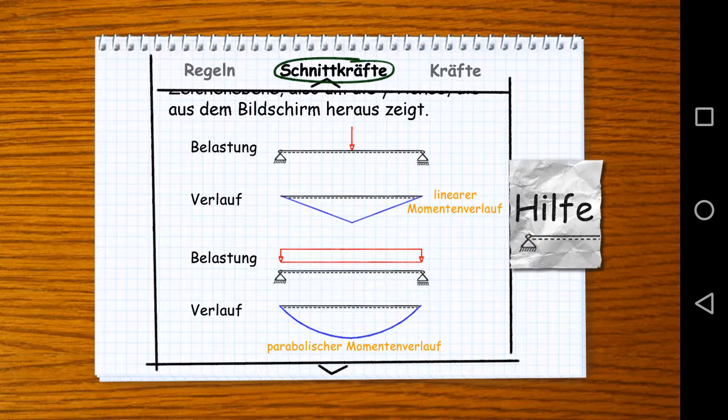Let's look at the example we have here. A single load in the middle of the beam. This beam is going to bend downwards. What I mean with that is that the point there, the middle of the beam, is going to have a deflection going downwards. But the left and right furthest positions of the beam, so on both supports, are not going to move. So we're basically going to have an arch opened upward, and that is actually what we call a negative curvature. So that arch opened upward is a negative curvature, and the opposite of it will be a positive curvature.